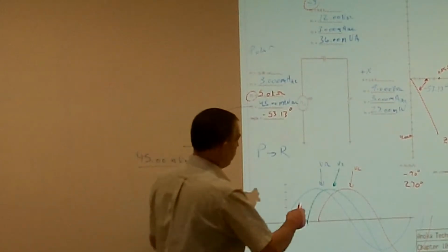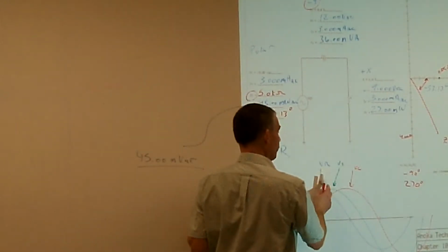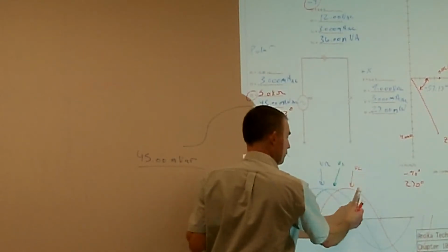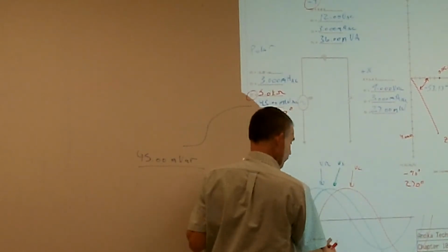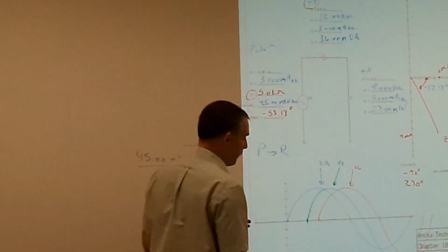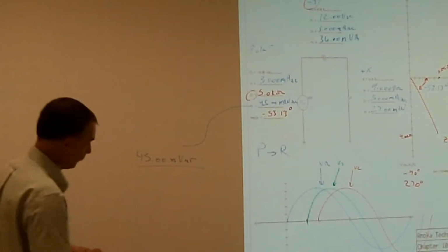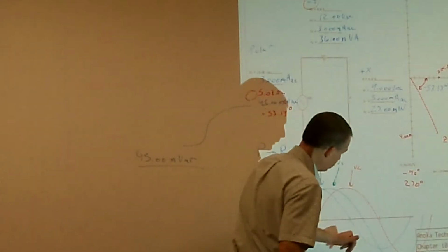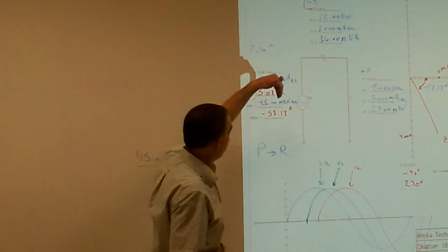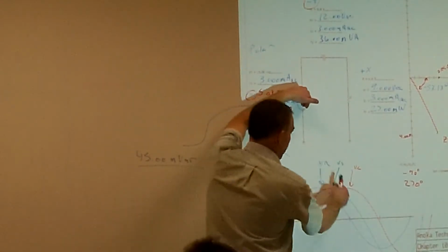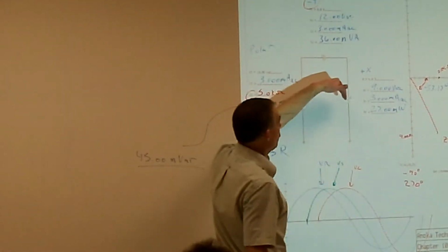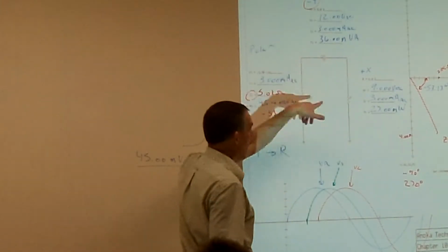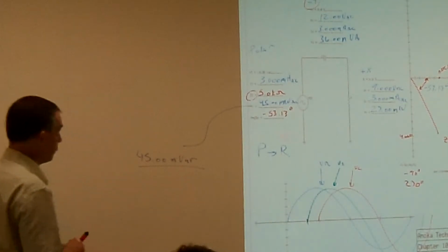And then if I did the math function, taking my voltage source minus VR, I could get my third waveform, which would be my math function, and on my oscilloscope I could see all three of those waveforms happening at different times. That's exactly what I would see on my oscilloscope: three different waveforms. So even though my voltage source is going up and down, the voltages across my resistor and across my capacitor are happening at different times than my voltage source.